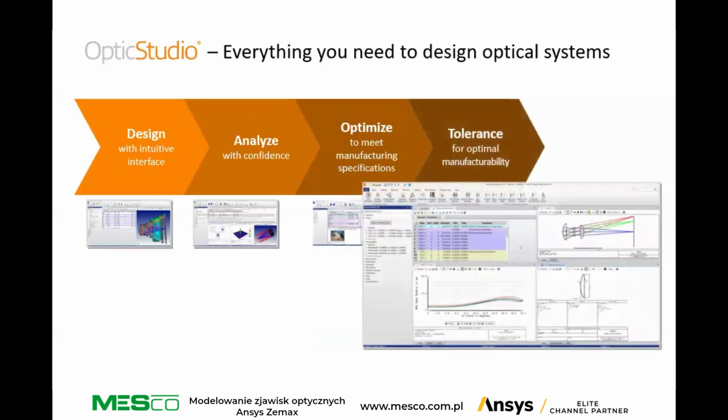But, well, we know that meeting the requirements, the specification, is not enough because each optical solution must be feasible and each optical design must be manufacturable. So with OpticStudio, you can perform a final tolerance analysis to ensure that your system can be manufactured. And for years, the Monte Carlo tolerance analysis in OpticStudio has been the standard for simulating how designs perform in the real world. So you can be confident that your system will meet the real world performance demands of your customer.